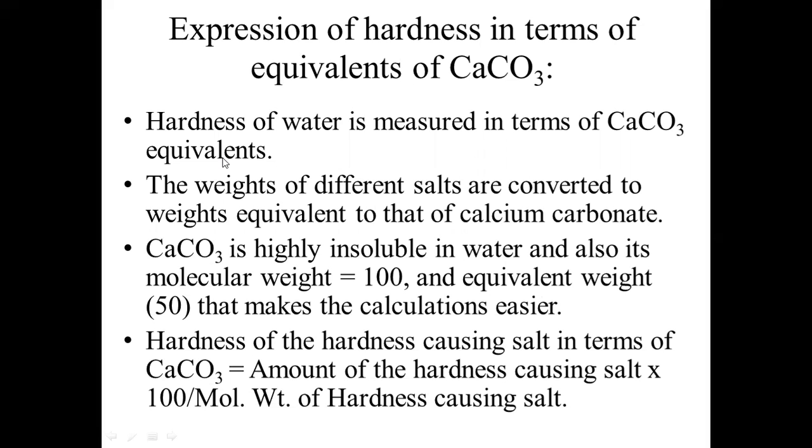That is a standard. Calcium carbonate is being used as standard in order to express the hardness of water. Now, the weights of different salts are converted to weights equivalent to that of calcium carbonate. CaCO3 is highly insoluble in water, and also its molecular weight is equal to 100, and equivalent weight is nothing but 50. That makes the calculations easier.